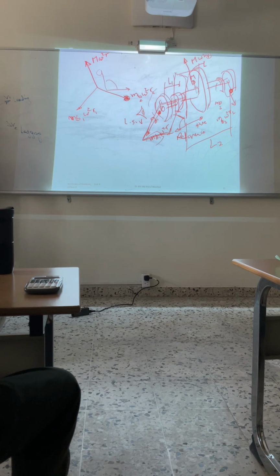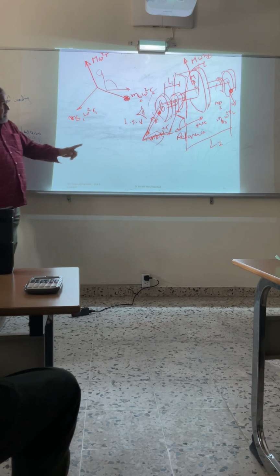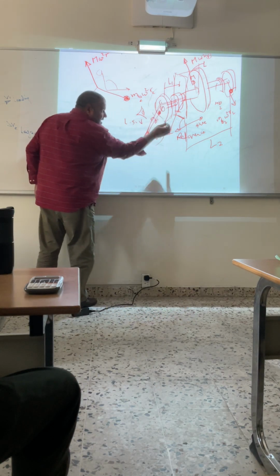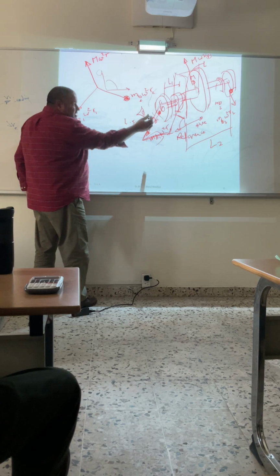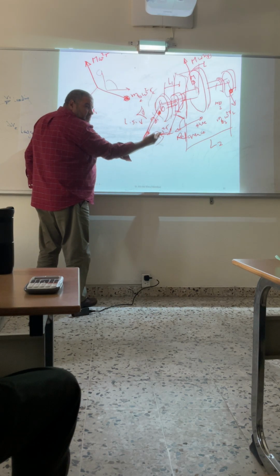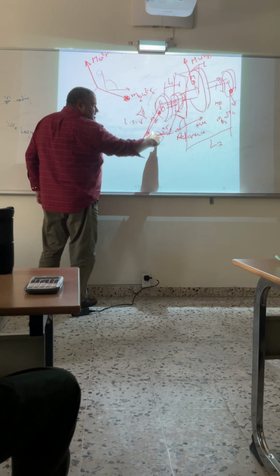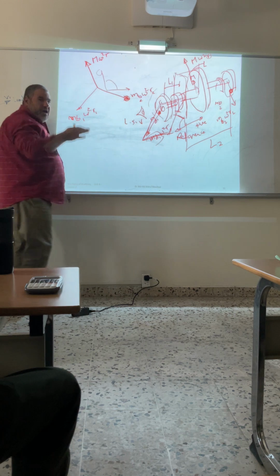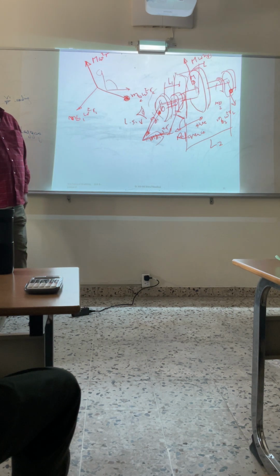Okay. Now, getting back to my business, I'm not going to draw anything here because I'm using the slide. Your vector is getting out of that inclined plane in that direction, right? This vector represents what, guys? It represents the moment, which is exactly equal to md1 omega square r times the distance L1. I'm not caring about the value now, I'm caring about the direction.